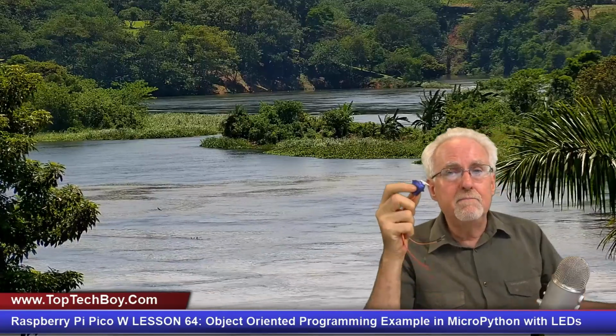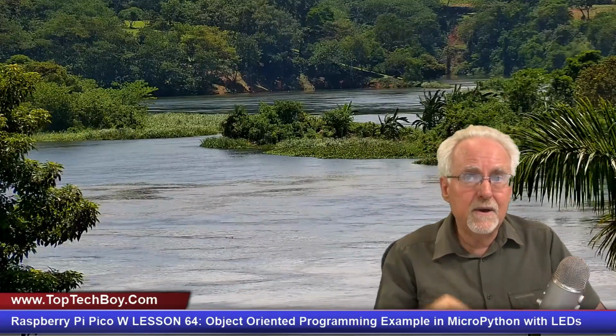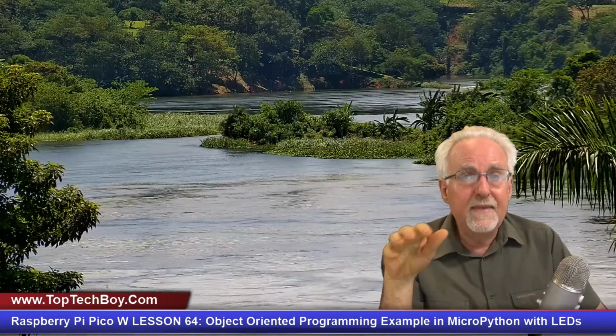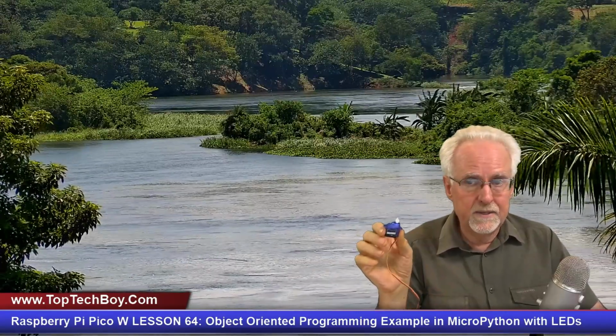Now, if you remember in MicroPython and the Raspberry Pi Pico, the way we were working with the servo before, we were setting up the PWM, and then we were calculating these values, and we were doing all of that stuff. And then every time that you wanted to use the servo to a position, you had to go through all those calculations. I want all that heavy lifting to be done up in the class and in the method. And then down in the using of it, it's just something like my servo or blue servo.pos, and then you pass it the angle you want.